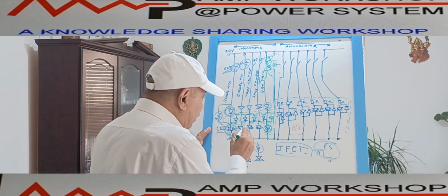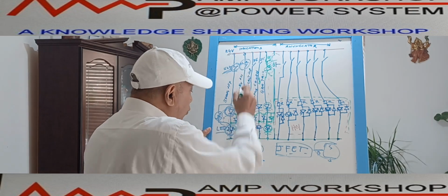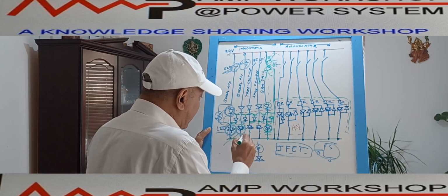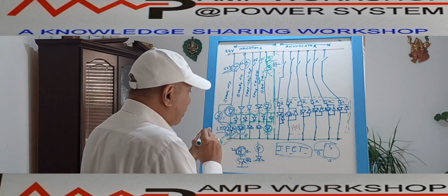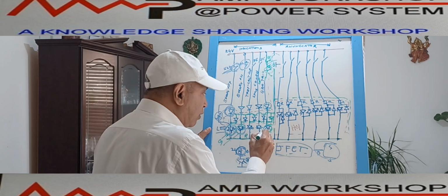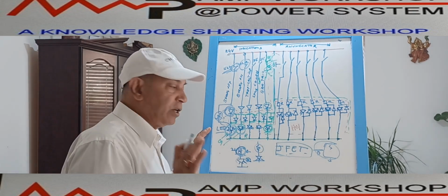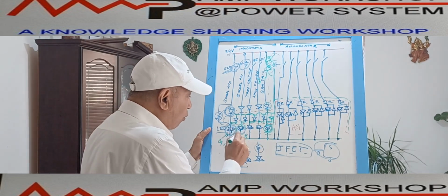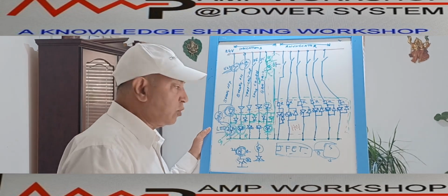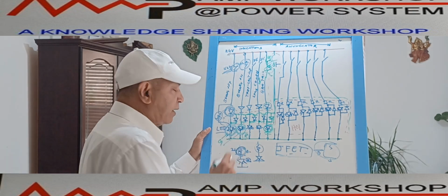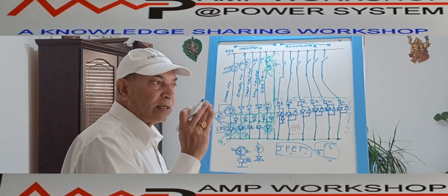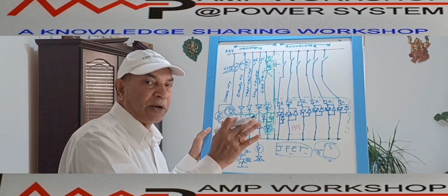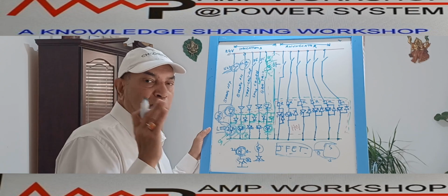That's why the breaker on status is represented by a red lamp, the off condition by a green lamp, and this other one is also green, meaning there is no abnormal condition. Some customers prefer a red color to indicate the circuit is charged, so that somebody does not operate on this circuit without a proper permit.